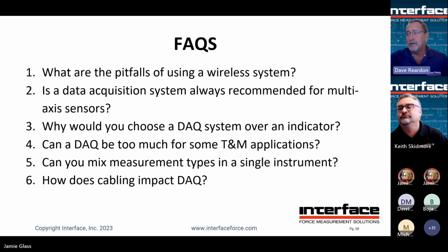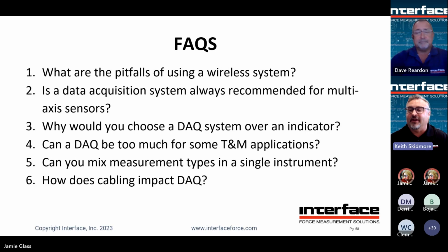It's not good for very fast data, and sensors that need to be synchronous. Also, there are limitations to transmission distance, and if you have it in a cabinet trying to monitor something, the signals may or may not be able to get out. But we do have things like repeaters and remote antennas to help that.